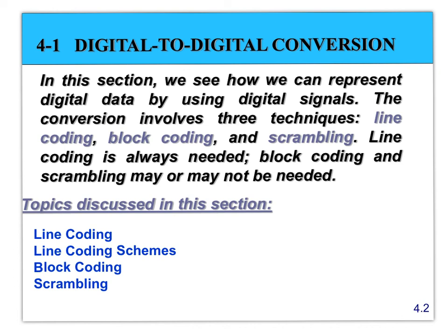So the main purpose of line coding, block coding, and scrambling, all these categories of techniques, is to make the bits that I transfer using either baseband or broadband, these digital signals and these digital bits, more error resistant. And we'll see how this is achieved. Okay?